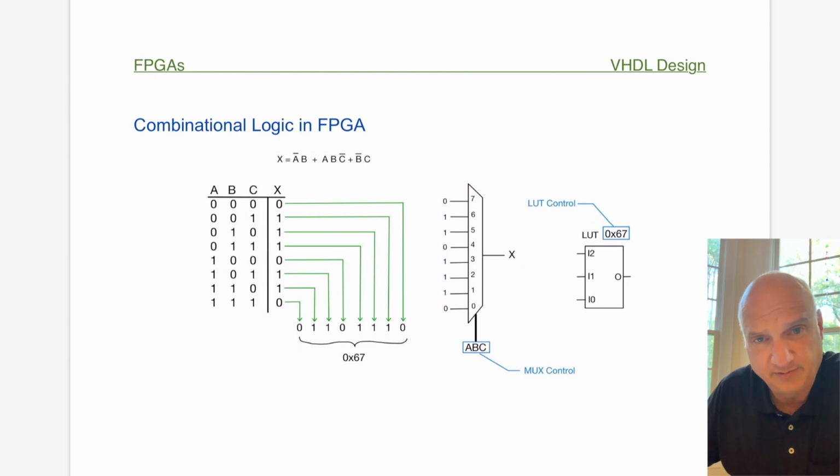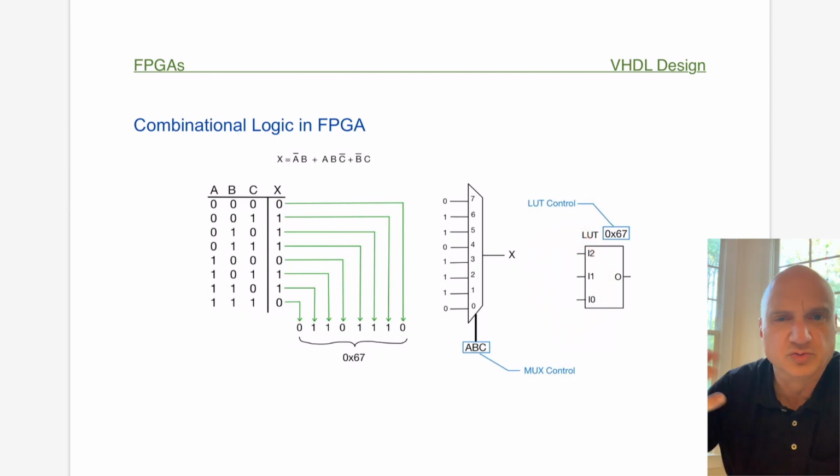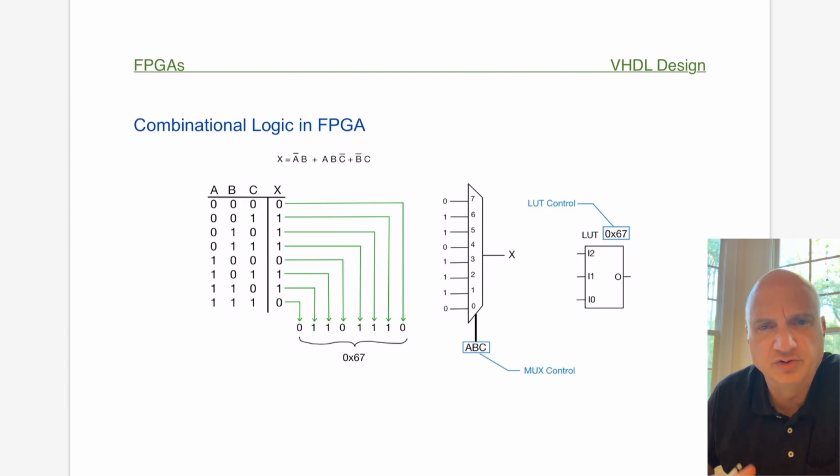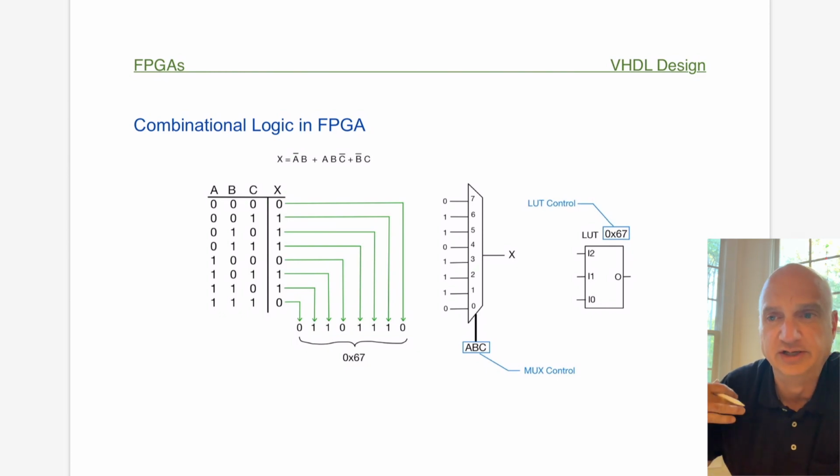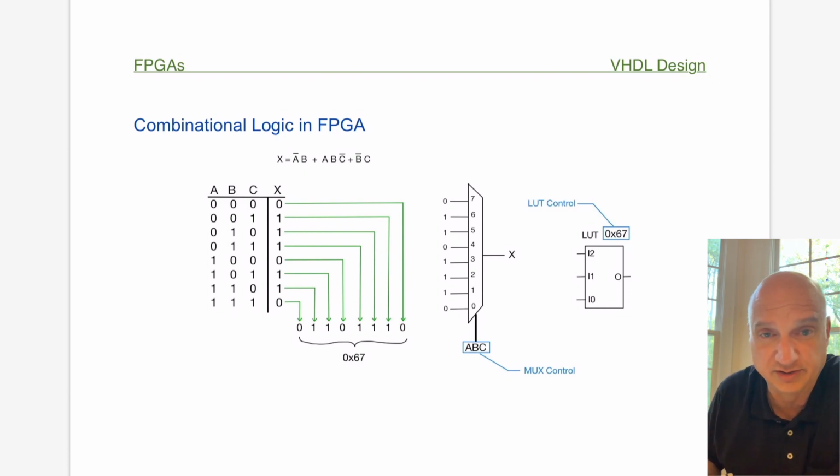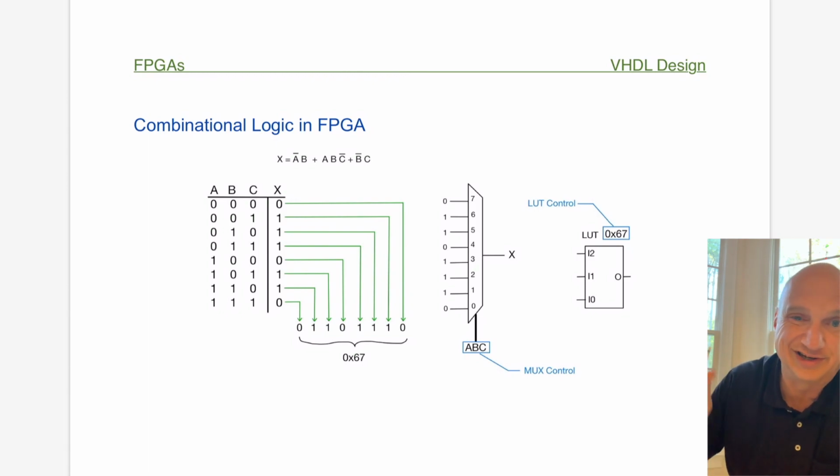If you have more variables than that, like in this case, if you have more than 3 for this particular LUT, then you would have to combine it with another LUT in order to expand that out, which will definitely impact the prop delay, as far as your signal delay, and affect the frequency that you could use in your device. But that's not something you tend to worry too much about, because when you're writing your VHDL code, you're trying to write code that is generic and applicable to lots of different designs, not just this particular chip. That way you can transfer it to different systems, and then you pick the chip that best fits or best utilizes the resources in your system. So the design comes before the chip.